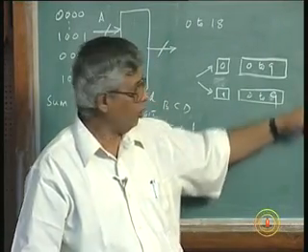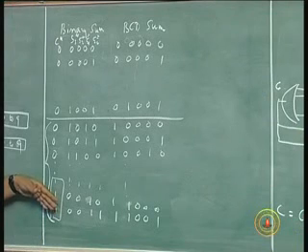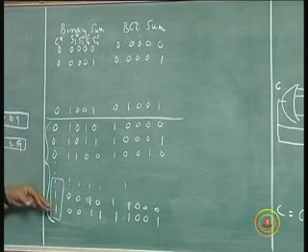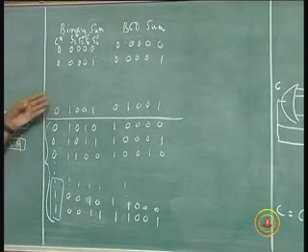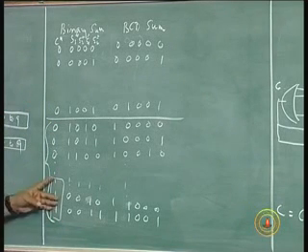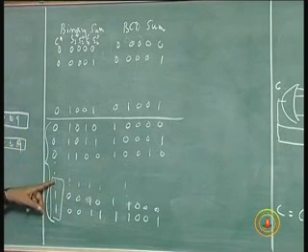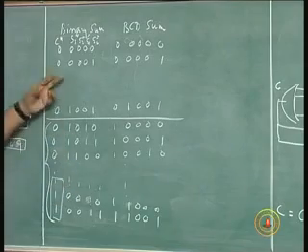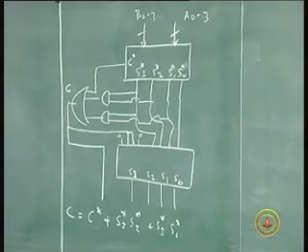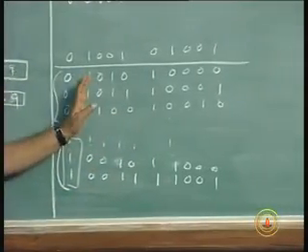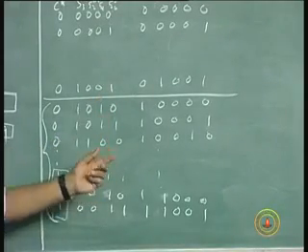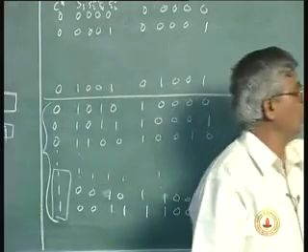Last 4 rows of my truth table, I want you to complete the truth table as an exercise, because this truth table will have 9 here, another 9 here. Now 10 to 19, 10 entries, 0 to 9, 10 entries, another 10 entries. In the last 4 rows of this, anyway you have to add 6, or when this and this, which is the last 2 bits of the sum, original sum, are 1, we need to add 6, or when the first S3 and S1, this and this are both 1.